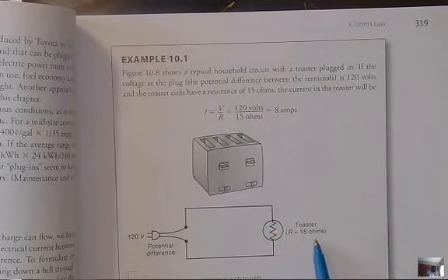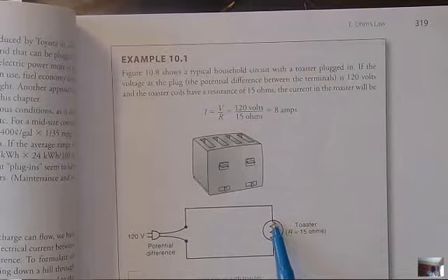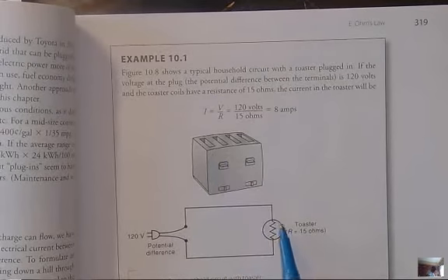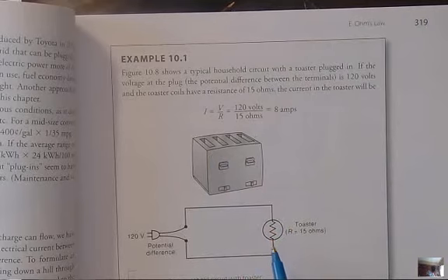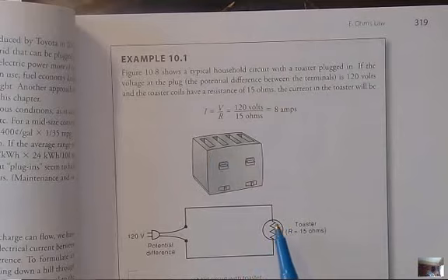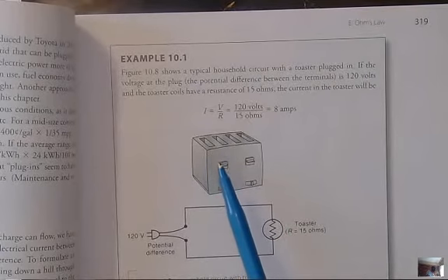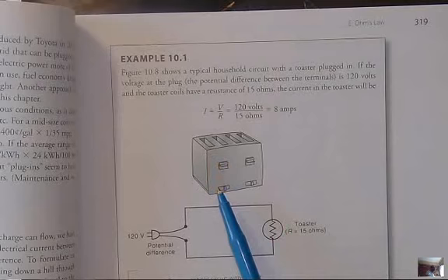They have a very high resistance of 15 ohms. So those toaster elements that are inside here on both sides don't allow the electrons to flow through very easily. The electrons have to force their way through, and when they do, they give off a lot of heat that's radiated out in the form of infrared radiation. The infrared radiation leaves the sides and penetrates into the bread to cook the bread,